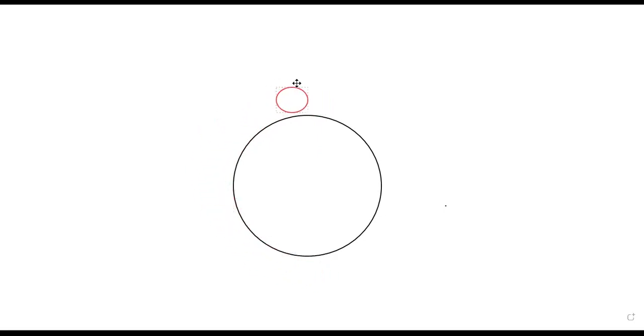That's why in this case we say that although the system is in equilibrium, it is in unstable equilibrium, because once we give a small displacement to the roller towards right or left, it will never come back to its original position. It will try to attain the minimum potential energy, because in this case the potential energy of the roller is maximum. So unstable equilibrium corresponds to the maximum potential energy of the system.